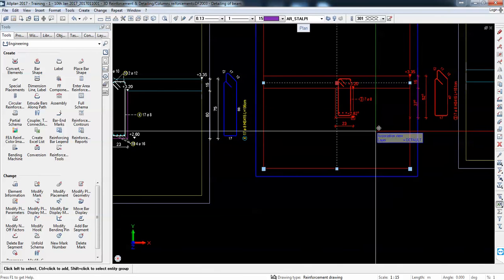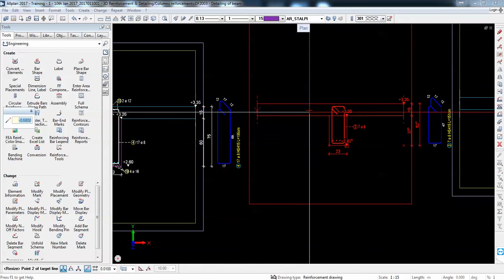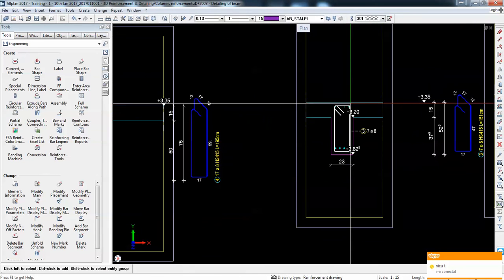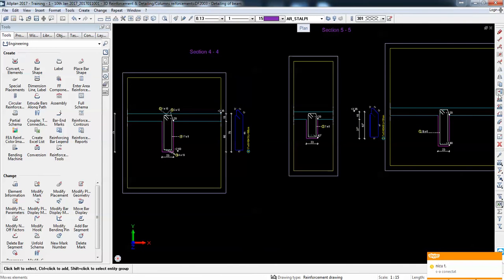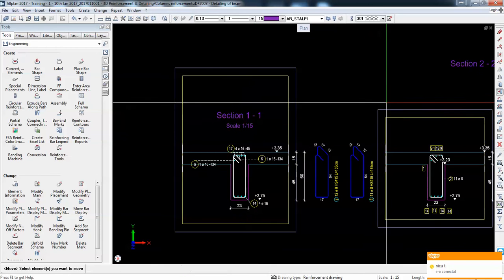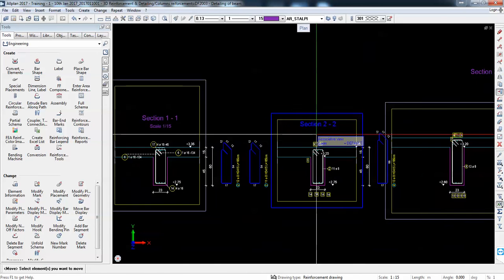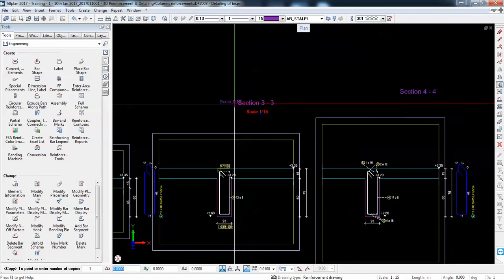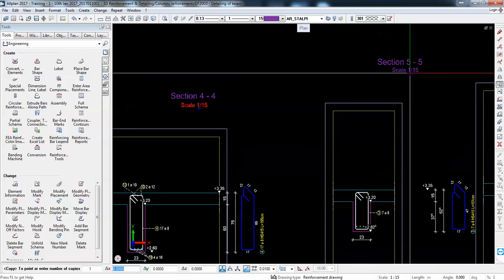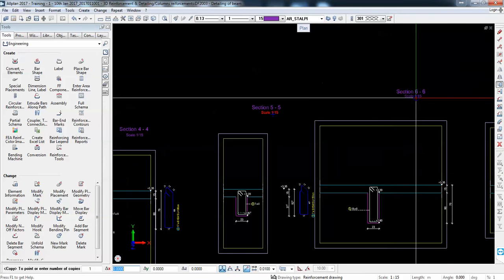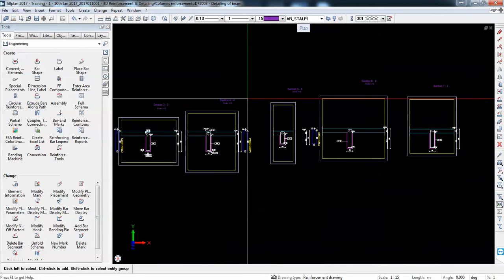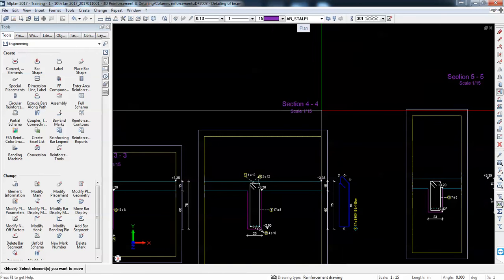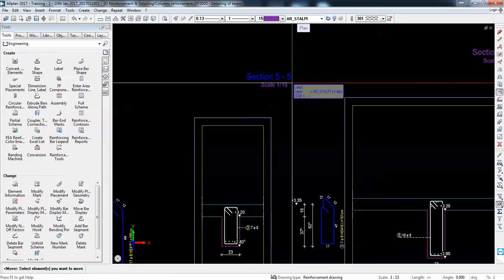If I decide it was too wide, the flange, I just pick up these endings and close them up, so I get more space for drawing. So there is some work behind obtaining nice drawings, but the main advantage is the information is correct. So it's the information that is live, and as in any projects, big or small, there will always be some changes from architecture, from HVAC. So it's important that we are able to do the changes in 3D or on the plans and get automatic update.